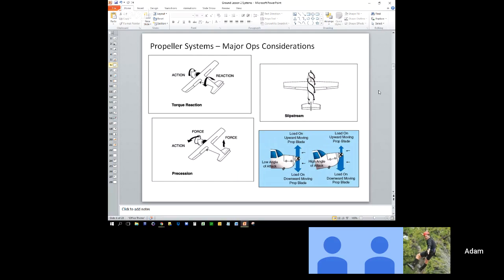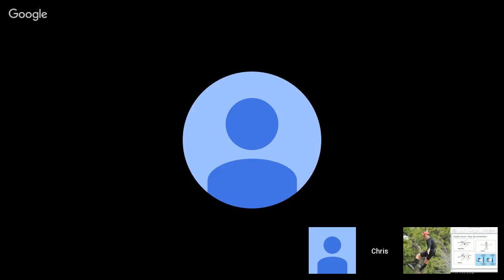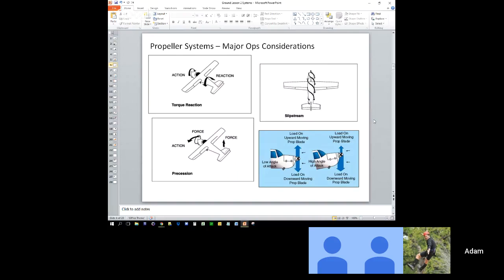Yeah, it's only when the propeller is spinning as fast as it can, at high RPM. Emily's question was, does it happen in descent? And the answer to that is no, or not typical, because it's a high power configuration. P factor is a high power configuration phenomenon when the prop is spinning its highest.